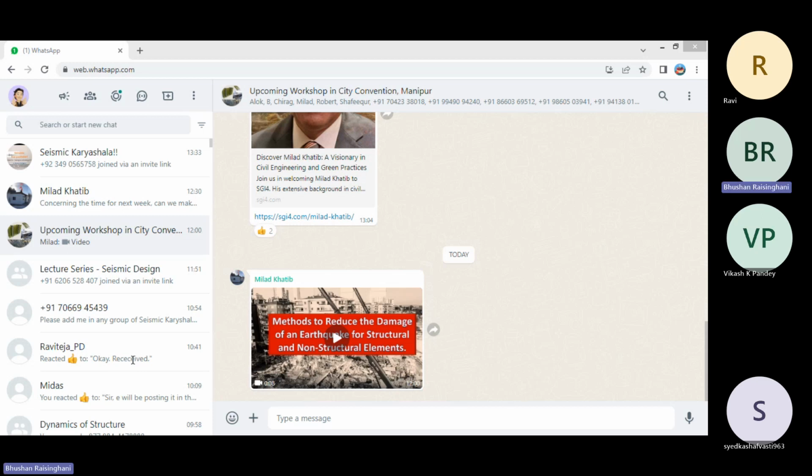So you can discontinue the boundary element after that level. And extreme fiber stress should be calculated in an elastic model using the gross section properties, as specifically mentioned here. So in this they are asking for gross properties of the section and an elastic model.